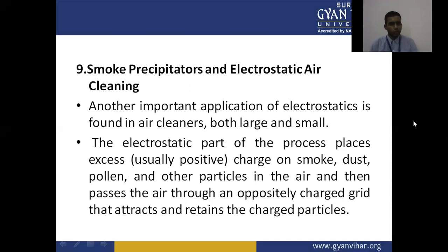The electrostatic part of the process places the excess, usually positive, charge on smoke, dust, pollen, and other particles in the air, and then passes the air through an oppositely charged grid that attracts and retains the charged particles.